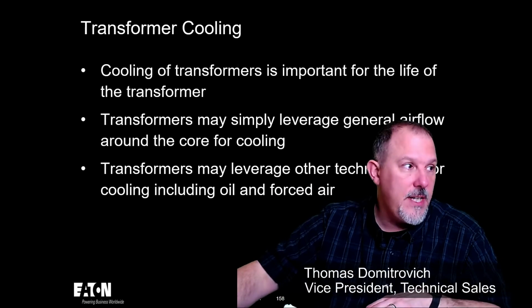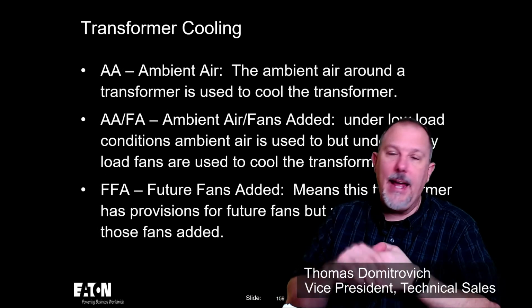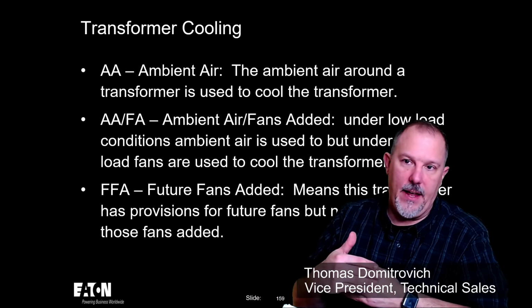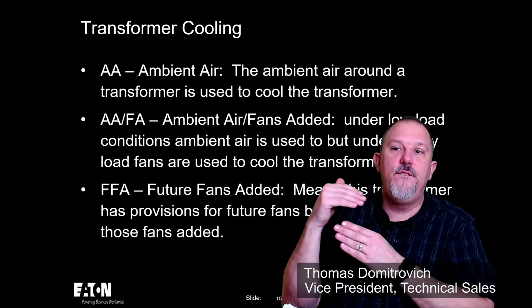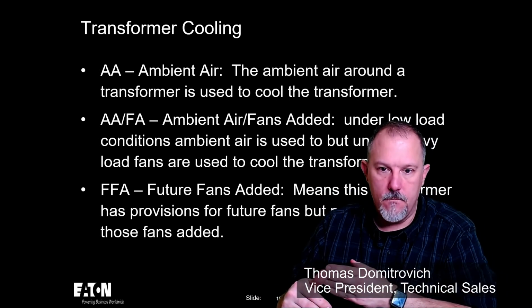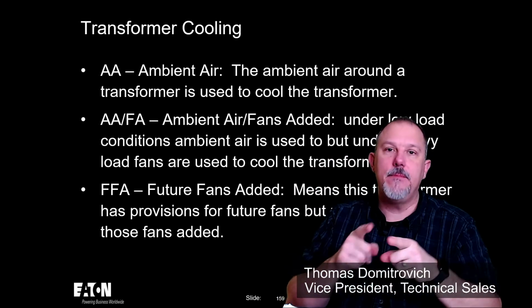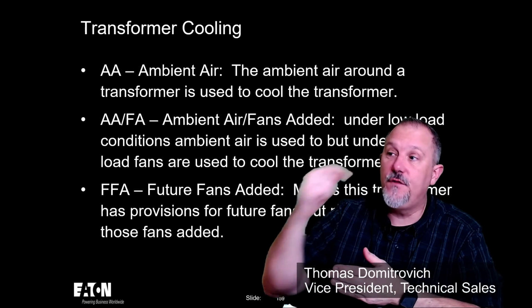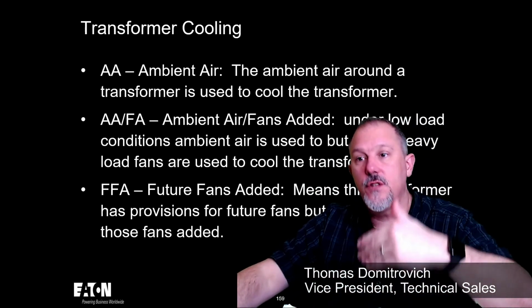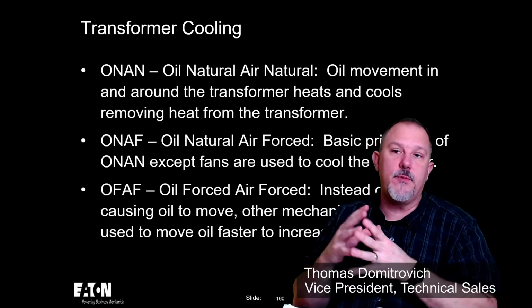So what you'll see on a transformer is AA for ambient air, AAFA for ambient air fans added. Yes, James Smith, FFA is future fans added, means it has provisions for fans in the future. So those are the types of ratings.